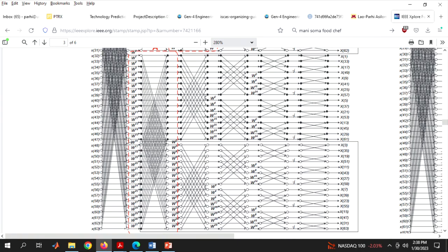Okay, so there are 6 stages, right? Log 64 to base 2. If you look at these, I think you are seeing my cursor, right? Yeah. So 1, 2, 3, 4. Okay, that's about it. And these ones are not there. So this is all minus j. So that fifth stage doesn't matter. No twiddle after the last stage. So really log n minus 2, I guess. Yeah, not log n minus 1. I could have taken log n minus 2 if I don't count the trivial multiplications by plus or minus j and plus or minus 1.